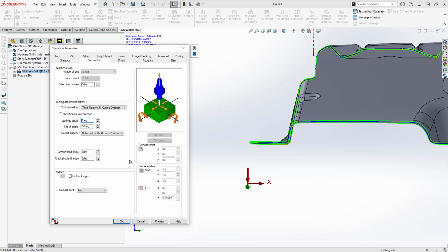So all of this together allows you to create a 5-axis simultaneous toolpath that, by the use of this tapered tool, will also do some chamfering. Basically, actively gouging the part to deburr the part.